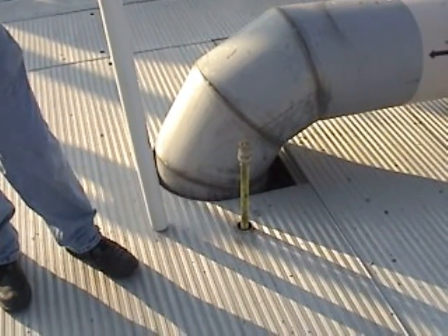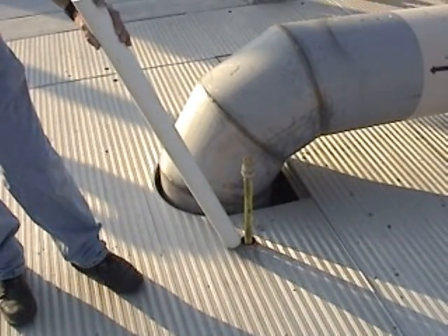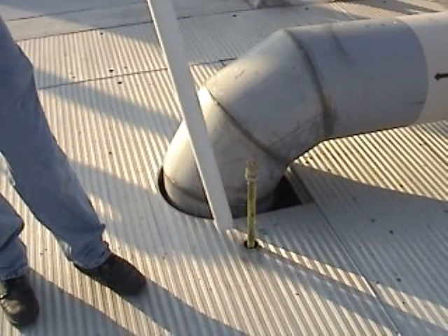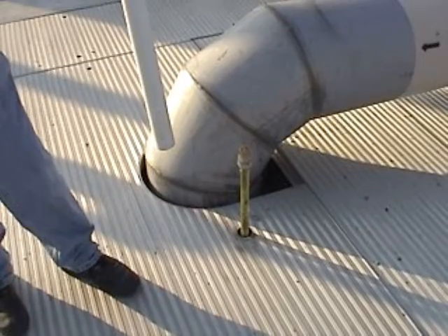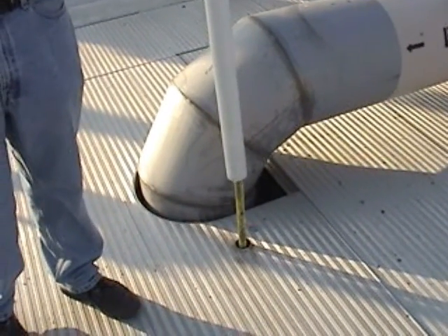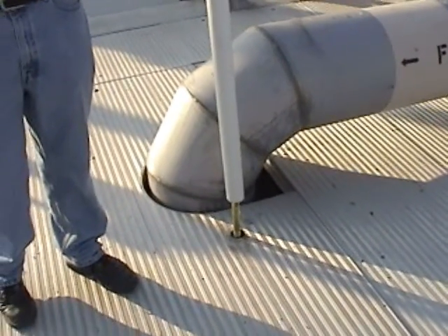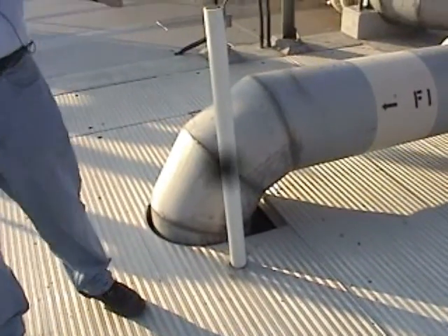We had talked about stacking some additional floats or modifying this in some way to where you could see the ping pong ball and then put a marker on here, you know, to tell you that you have a problem with the filters. But over time we've determined that that's just not a problem. There's so many other things that you would see before you saw the ball float to the top of that pipe that we just kind of left it alone.